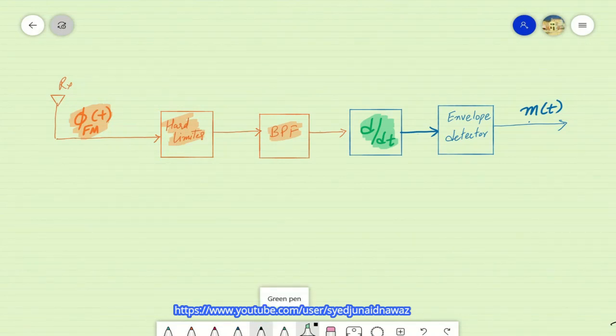So as a response, we received a signal which was both amplitude modulated and frequency modulated. After translating the variations from instantaneous frequency and phase of the modulated signal over the amplitudes, we employed an envelope detector to detect the envelopes. That is, over the envelopes, the information signal was represented.